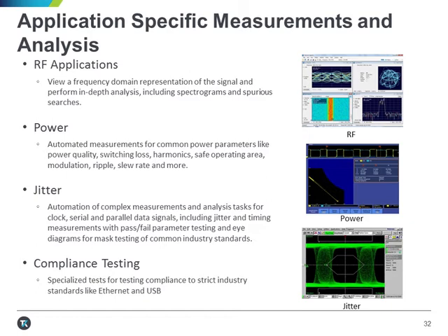If you're getting involved in power supply designs or evaluation, you may want to look into power application modules. These allow you to measure specific power parametrics such as harmonics, switching losses, and safe operating areas. These applications are available starting with mid-range oscilloscopes in the 100 megahertz range.